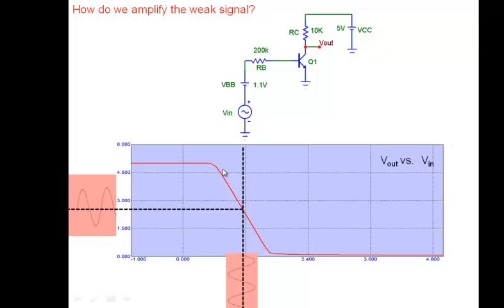You will find the voltage is constant. It's no longer responding. You're increasing the input voltage here and your transistor now goes here. It no longer responds. The voltage is constant. See, amplification means if I increase the input, the output should increase. If I decrease it, it should decrease.